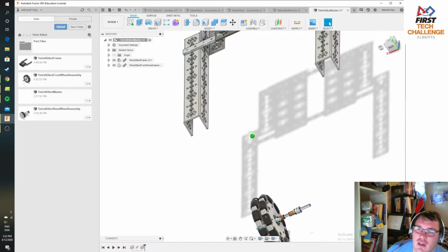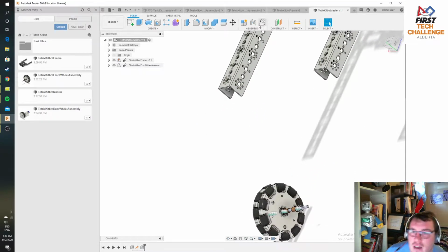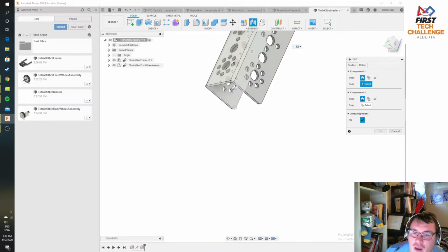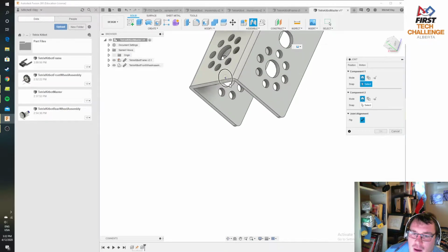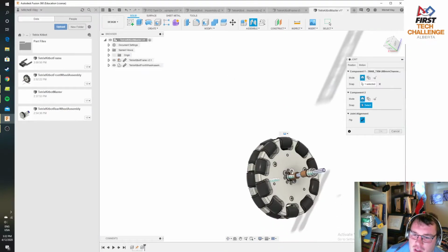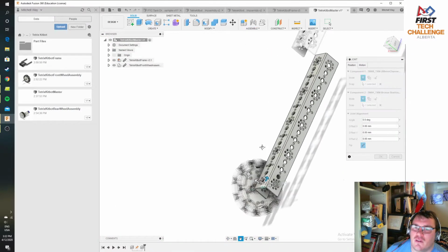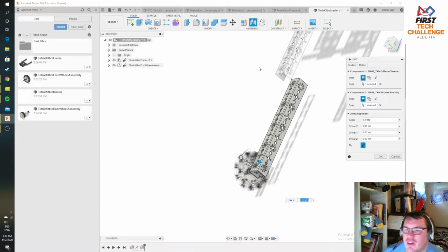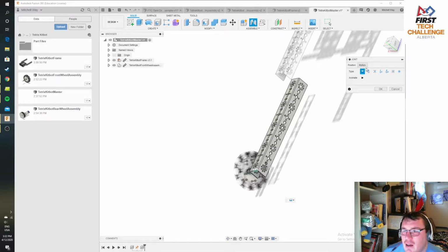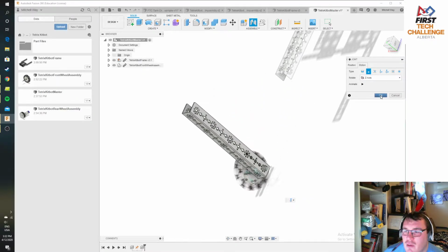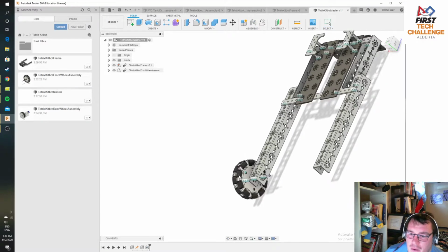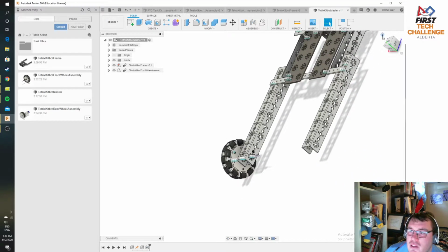What we're going to do with this is I'm very simply going to drop this guy in here as a joint, and I'm actually going to grab a spot to drop this in as a rotational joint, there and there. Now, you'll notice that because of the order I clicked things in, it brought the bar from the frame down here. I don't necessarily want that, but I do want a revolute joint. When I press OK, you realize that I've now got this whole thing set up here.